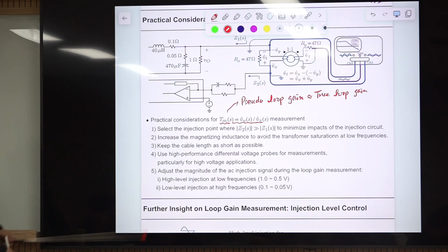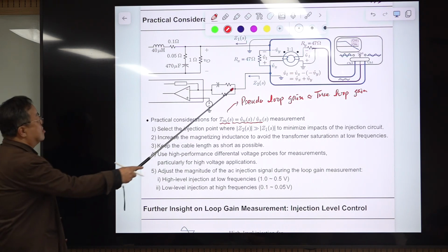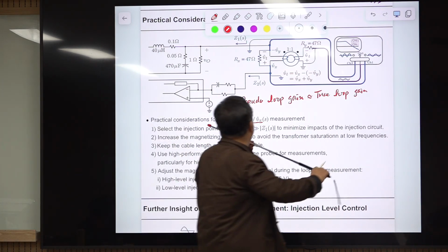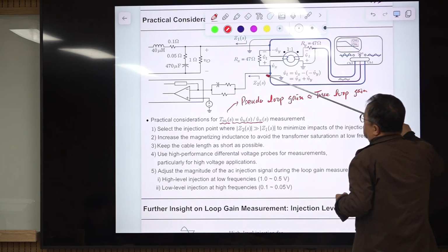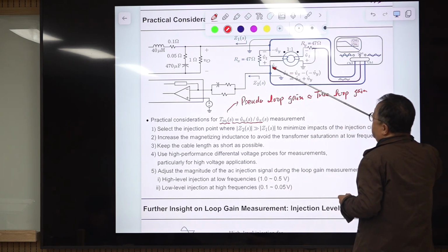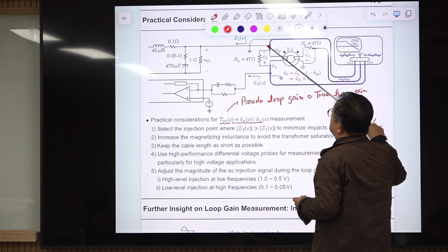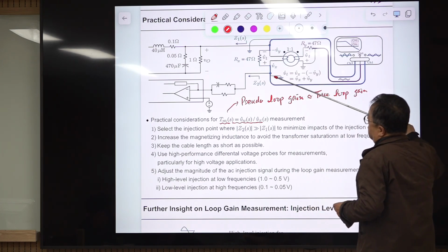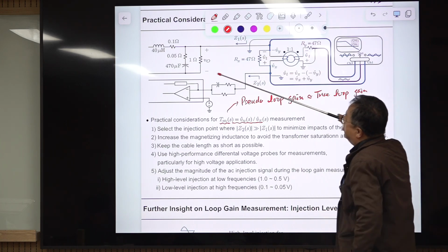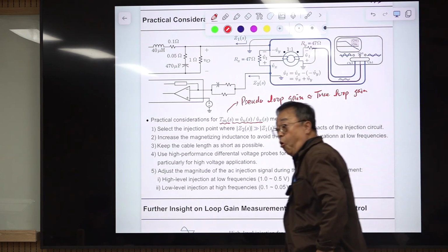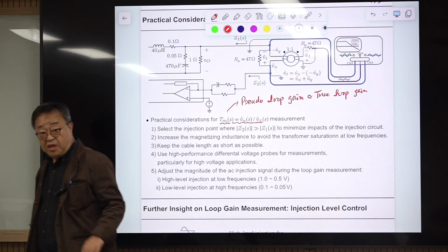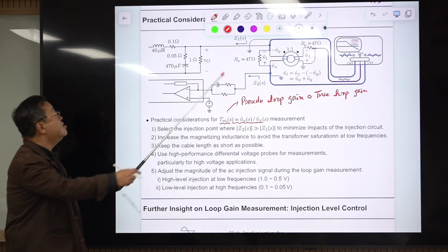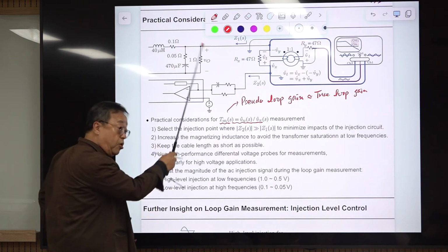The first one is this. Impedance G2 is the impedance seen looking into this. This is the node where Vx hat is connected, and this is the node where minus Vy hat is connected. So you are seeing this impedance, which is the input impedance of the op-amp compensation circuit. It has very large input impedance in general, and this is the output impedance of the converter.